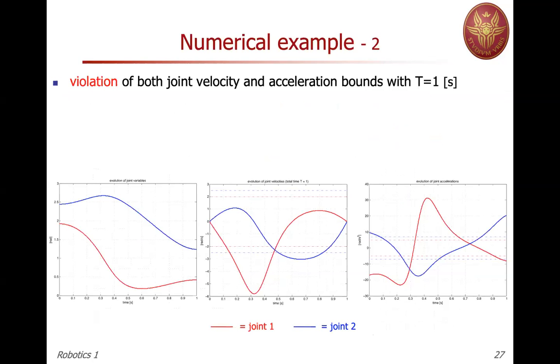So if you do that, you obtain this type of evolution for joint 1 in red and for joint 2 in blue. I haven't put any limits on the joint range, but if I had violated some joint limits in terms of angles, then no matter how I speed up or slow down the motion, I will trace again the same joint path, because I'm tracing again the same Cartesian path, and there's a unique solution in the inversion.